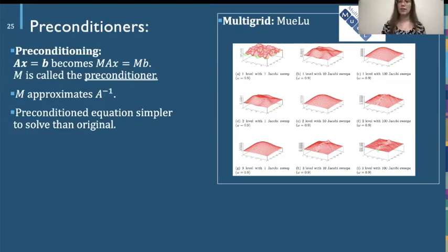So a multigrid divides your problem discretization into a set of coarse grids and fine grids. It works some on the coarse grids and some on the fine grids, and uses projections to use the information from different solutions to accelerate the different solutions on other grids in the solution of the whole problem.